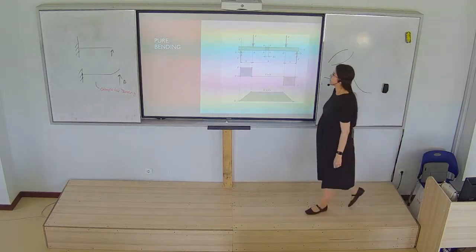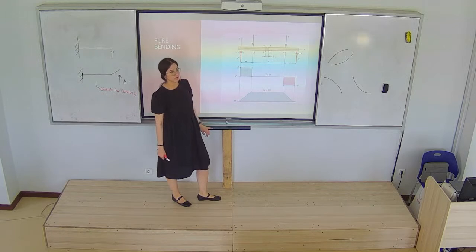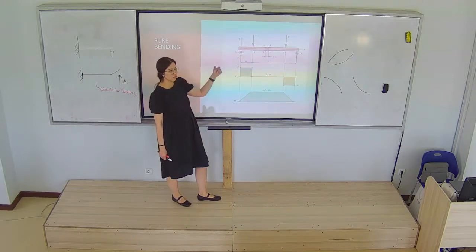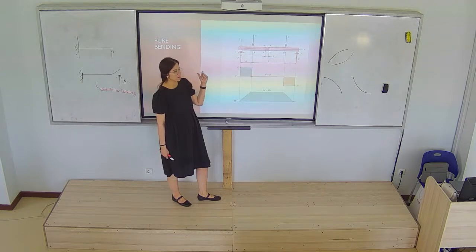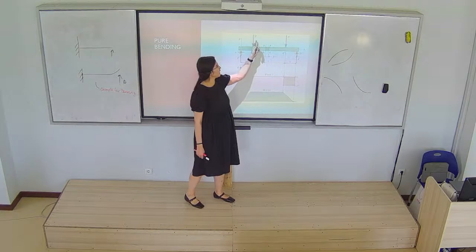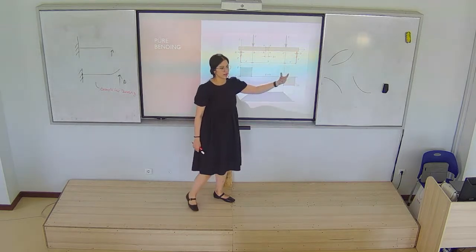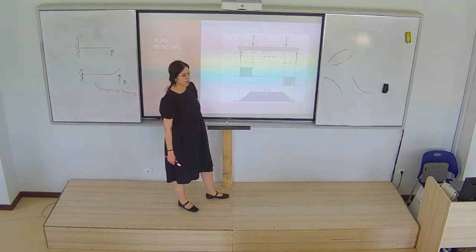So, as an example, we took a beam. Which kind of beam? What is the name of this beam? Simply supported beam. We call it simply supported if we have two supports on both sides: this one is a pivot, this one is a roller, and we have a P load, which is at a distance A from our support. Yes, this is the length of the arm.